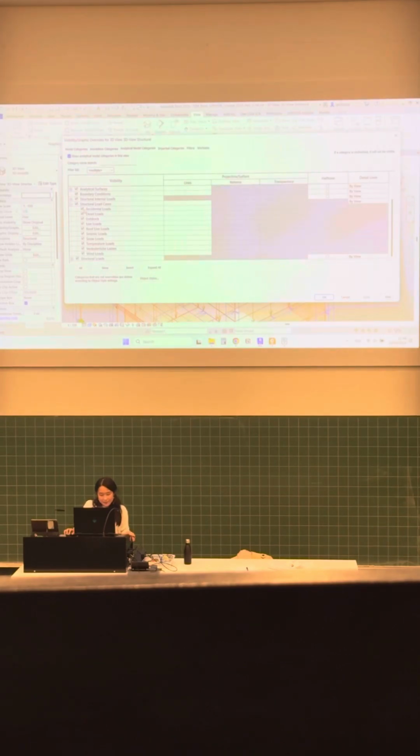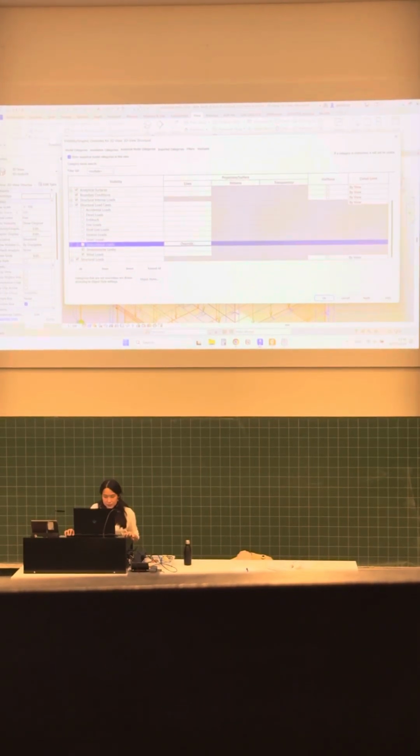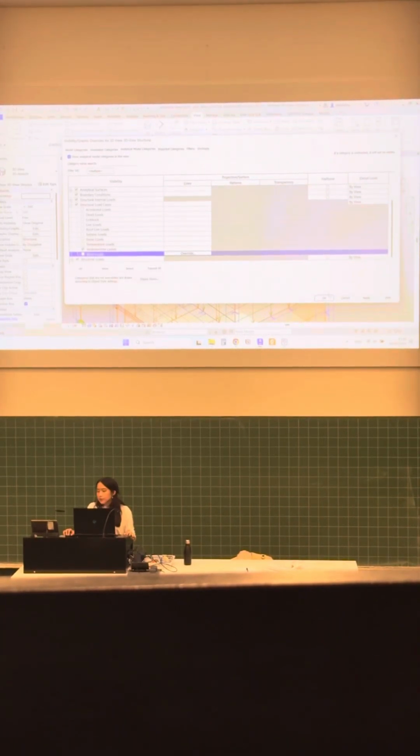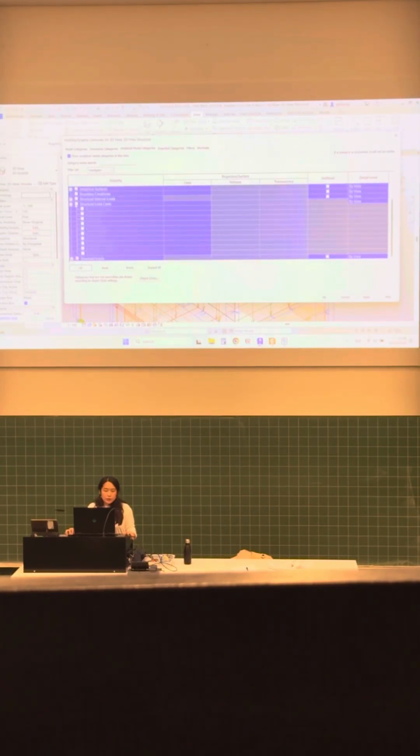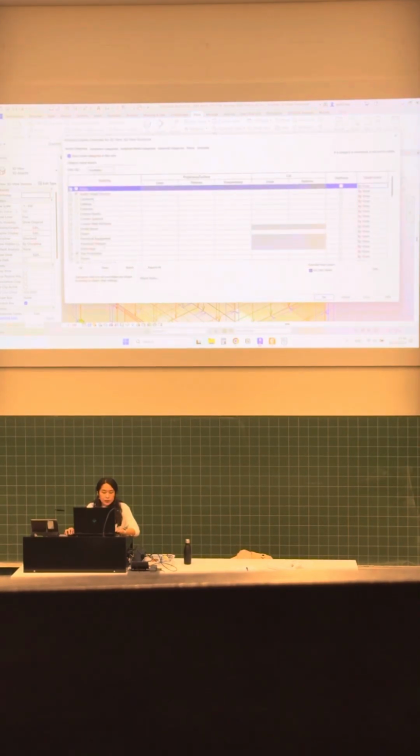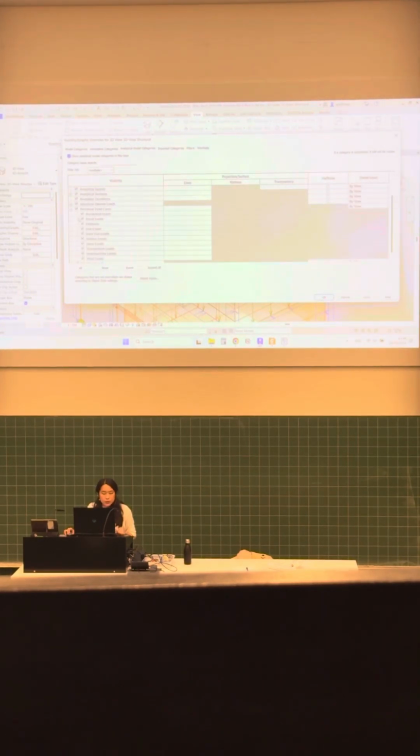Okay. Well, you can filter them, but again, it depends on how you defined it, because sometimes, for example, dead load can have two loads. It may not work, but let's try. For example, variable load. I will untick them. Just a second. Annotation, analytical model categories, analytical structural load cases, and, for example, I untick everything except the variable load.